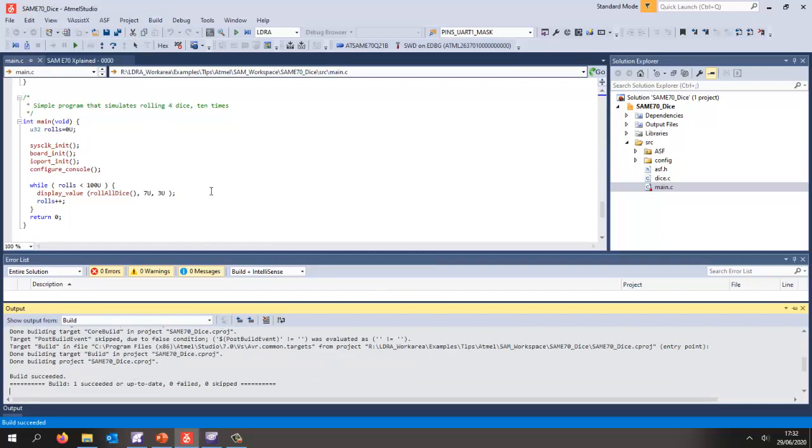And what I'd like to be able to do is to first of all analyze this code and find out, well, is it good quality? What's the cyclomatic complexity of the functions? Is it compliant to MISRA? And then I'd like to be able to execute this main, and as it executes, find out how much of the code we have actually exercised. And if we haven't got 100%, then I'd like to be able to use the unit testing tool tbrun in order to complement that coverage.